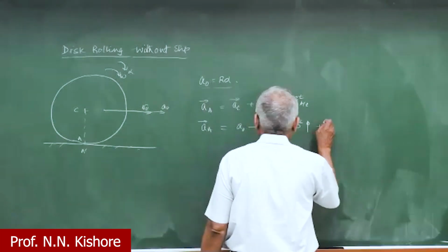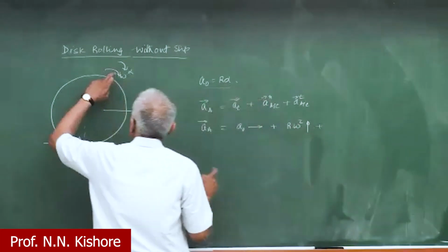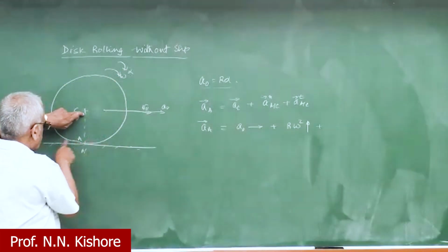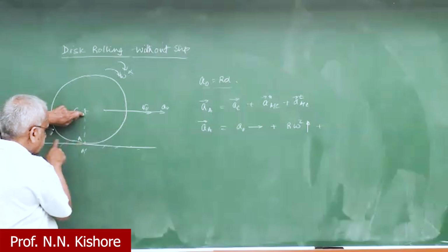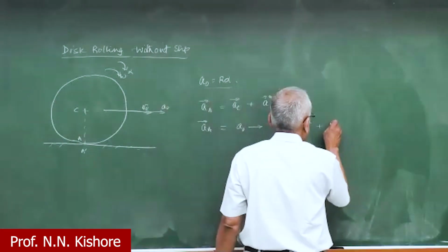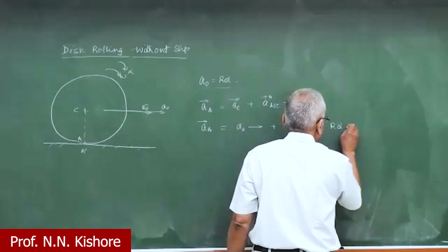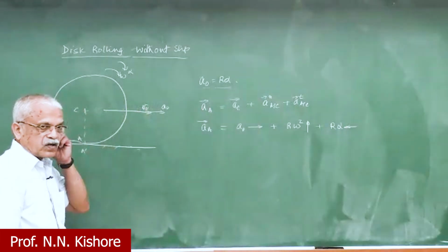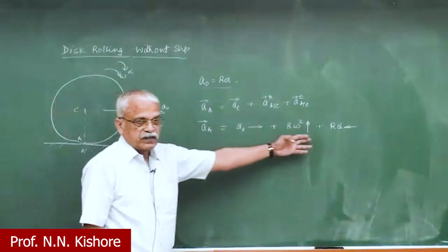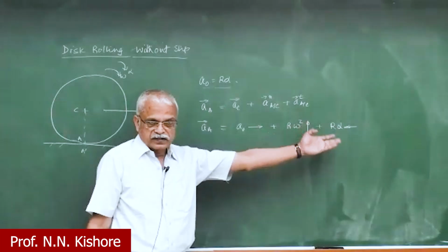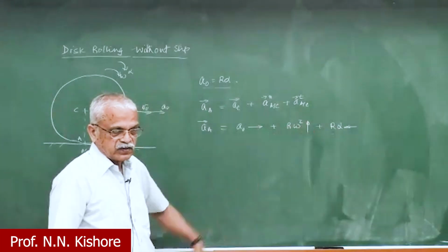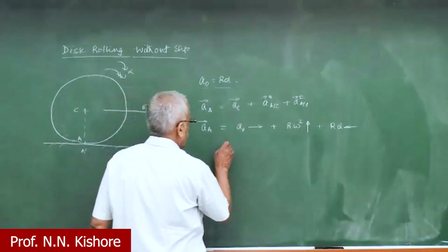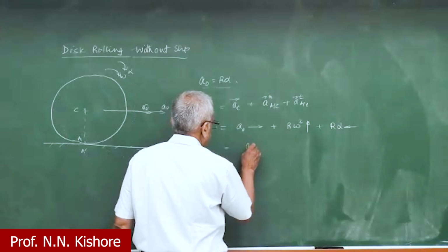And the tangential component is again a relative component. So with alpha, if it is rotating about C, the tangential acceleration of A will be R alpha and going to the left. So this is how we can show a vector equation. I'm showing the magnitude and the direction. This is as good as your IJK, and in fact, this is even faster. So we'll collect the terms here.